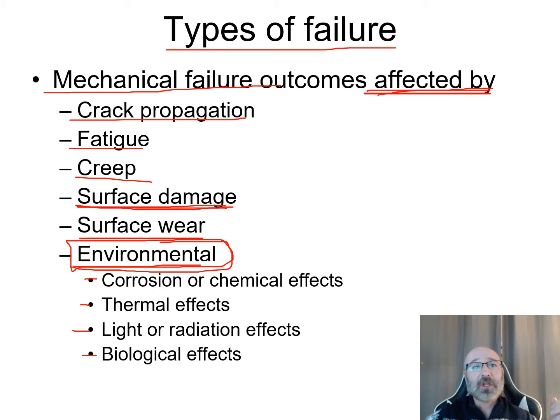Now we can take a look and say, well, this is typically going to be used in this climate, so thermal effects are going to be of great importance because we're going to be in a warmer climate. Or maybe we're going to have this in Alaska, and thermal effects up there are going to be different because it's going to be really cold. So you might have extreme cold due to where the product is going to be used primarily. We've got to think, well, maybe somebody else is going to use it elsewhere outside of that type of environment. So you need to understand the range of temperatures that could affect this.